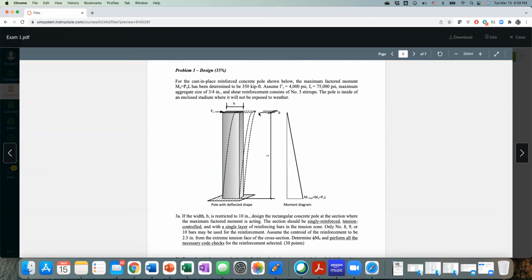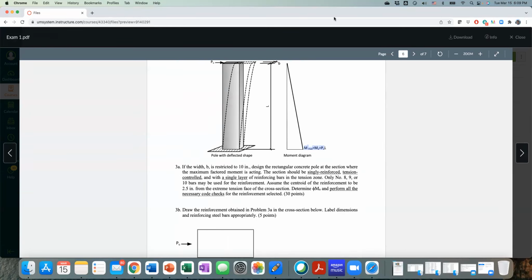So when I do that, we exert a max moment at the end of the support here, right? But be careful: when I push down this way, I'm bending it in a negative direction. That means if I draw the section right here, like that, you think about the bar should be on the tension side.